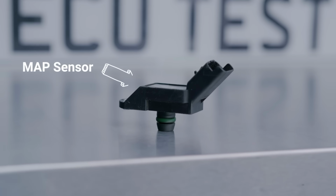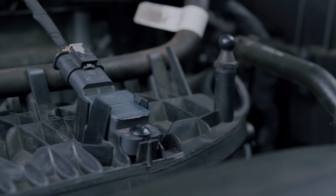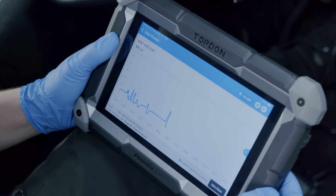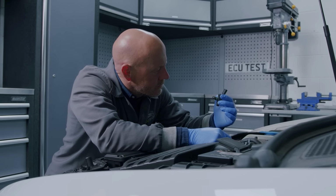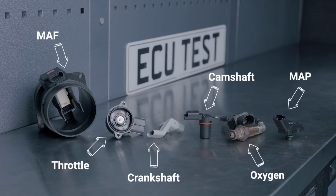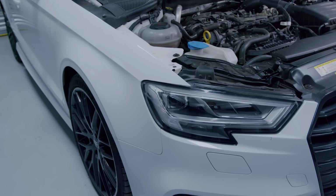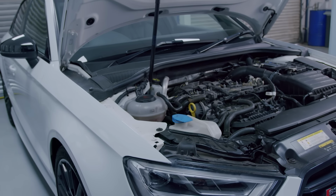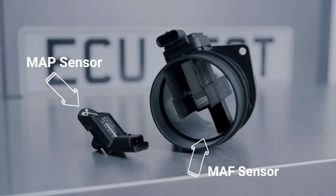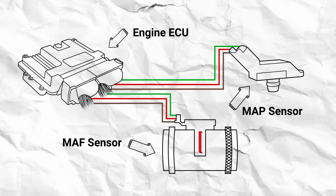The manifold absolute pressure sensor, or MAP sensor, is a key component in the engine's combustion cycle. It measures the air pressure within the intake manifold so that the engine control module knows exactly how hard the engine is working. The ECU uses this information along with other sensor inputs to calculate optimal fuel injection and ignition timing. It's important to note that not all vehicles have a MAP sensor. Almost all modern fuel-injected vehicles have either a MAP or a MAF, a mass airflow sensor. Both help the ECU determine the proper air-to-fuel ratio for combustion.